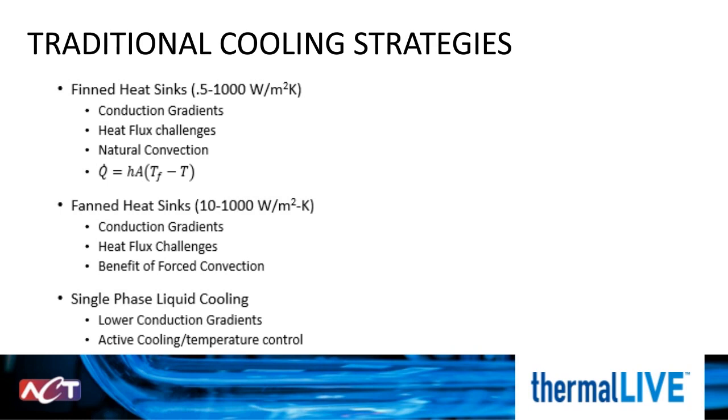The last, but not least, off-the-shelf cooling strategy for power electronics is the liquid cold plate. The single-phase pumped liquid solution has the ability to reduce conduction gradients, as well as offering temperature control. However, it struggles with high heat fluxes and temperature uniformity.